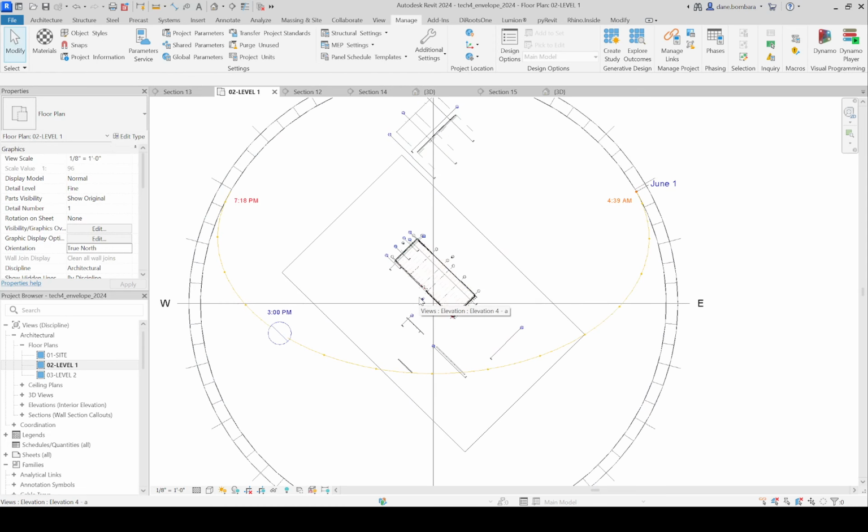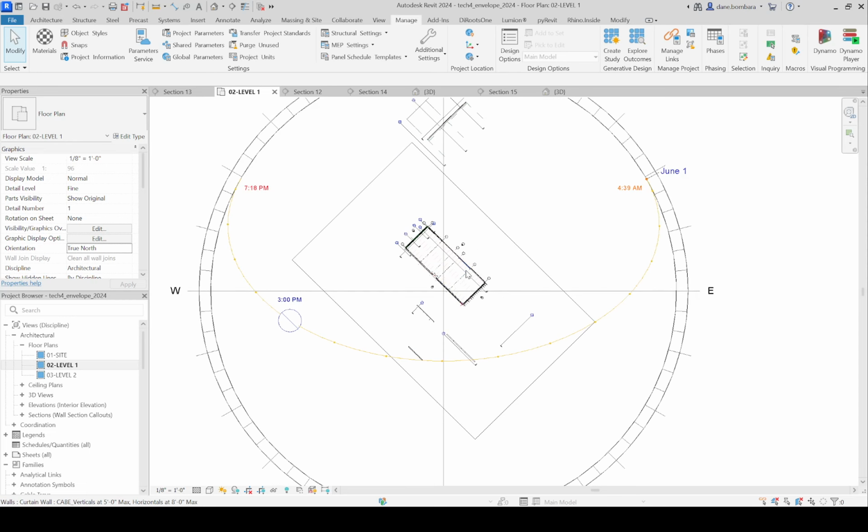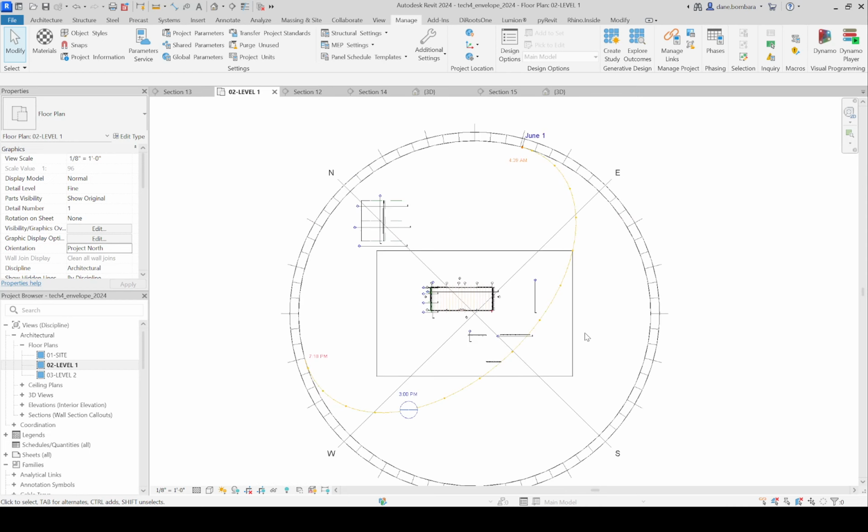you'll see that nothing changed about the compass because I'm rotating true north, but my whole project rotated. So if I shift back to project north, my project goes back, and now north is 45 degrees to the left. So you're going to screw that up. Just make sure that when you rotate it, you look at north and it's the way you want it to go. And if it went the exact opposite way, like I do 50% of the time, undo it and then do it the other way. But now it's facing north, so that's how you rotate and get the right north.